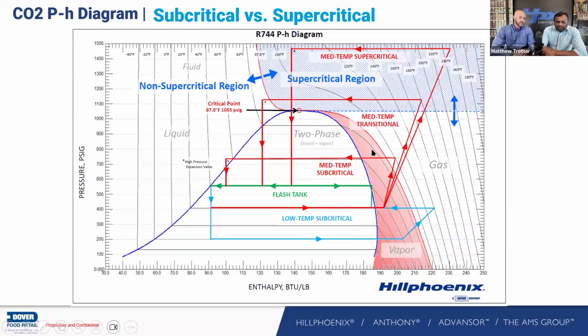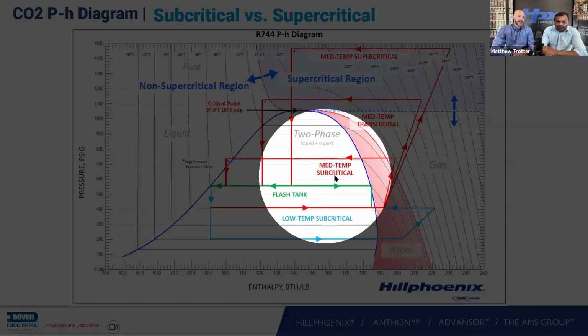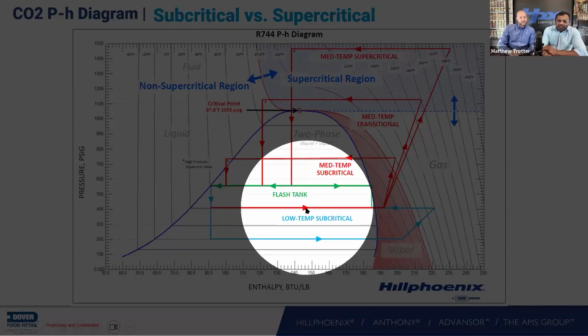pressures. In HFC systems, you have 2 different pressures. If you take a medium temp only or low temp only system, you have a suction pressure and a discharge pressure. So there is no intermediate pressure. That's one difference in a CO2 system. So why do we do that?